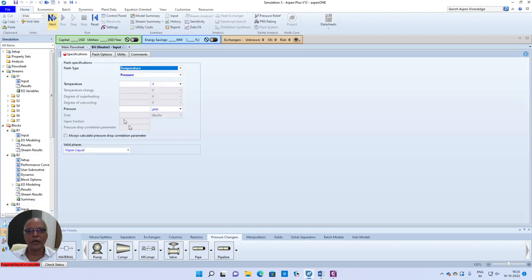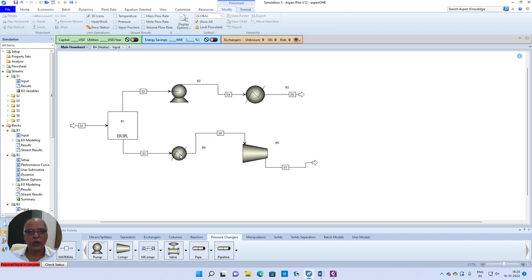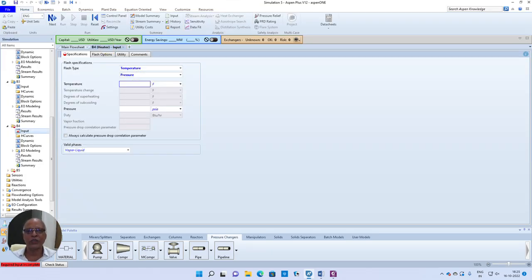Now coming to the second option, we are trying to heat or vaporize the input liquid ethyl benzene to some intermediate temperature, because when you compress, there is likely to be an increase in temperature. Finally, we would like to have the same 752 degrees Fahrenheit at the exit. So we may not have any idea about this temperature. So let me presume some value, say 500 degrees Fahrenheit, for example.